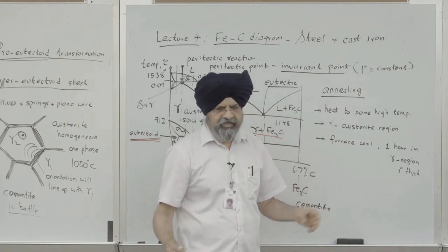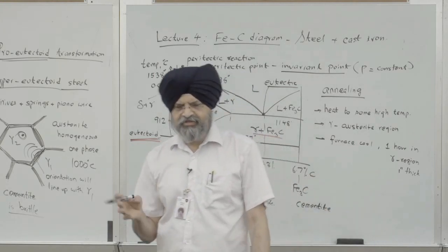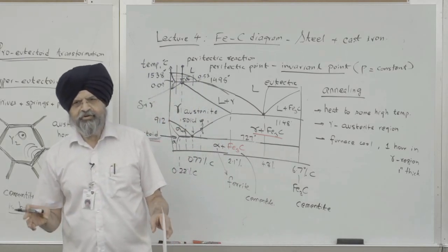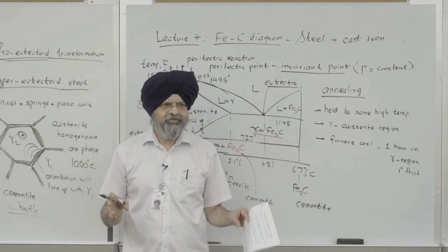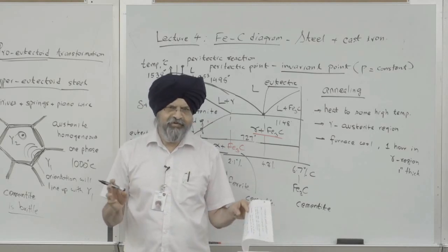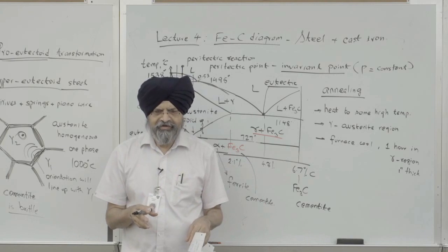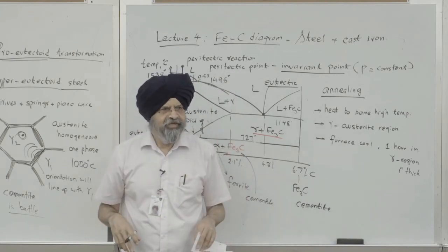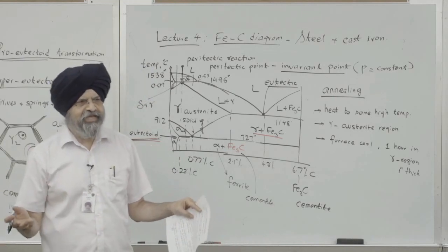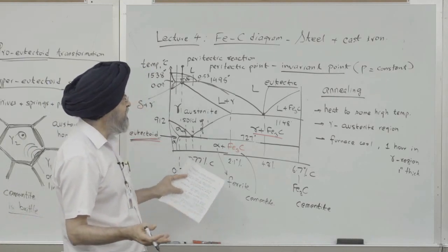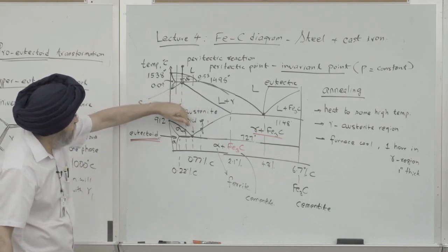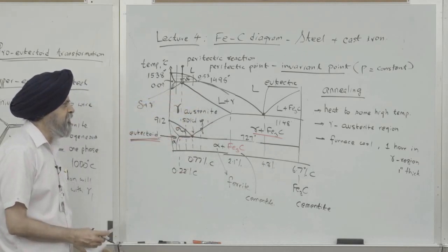So in India, I talked to some engineers in this low-tech factory. So how do you anneal your steel? They actually make a bonfire, and somehow they put the steel in the bonfire, and then they just go home. Next morning, the fire is gone, and they pull the steel out of the ashes, and it's been annealed. So annealing is heating to the austenite region and cooling slowly.